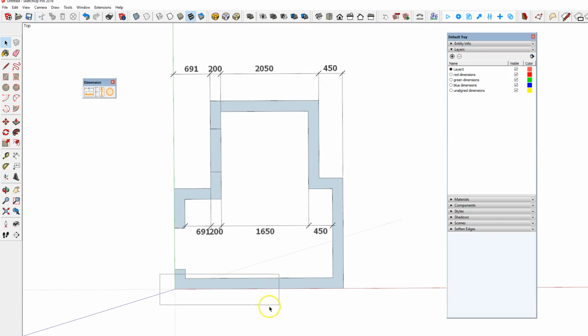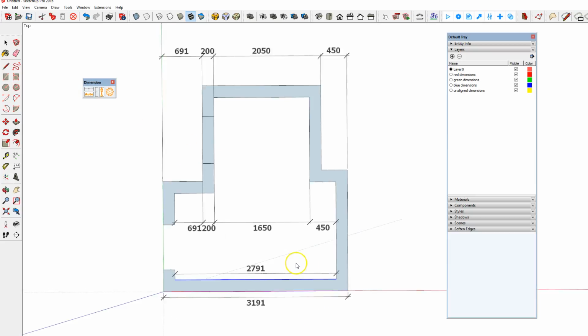So I want to add these two here as well, so just select those two, hit the button, then it adds in the internal and external, and you can do the offset here. Let's type in 100. I actually interfered with that, so you have to do it immediately afterwards. You can't move anything, so click my button, type in 100, and there you have it offset.